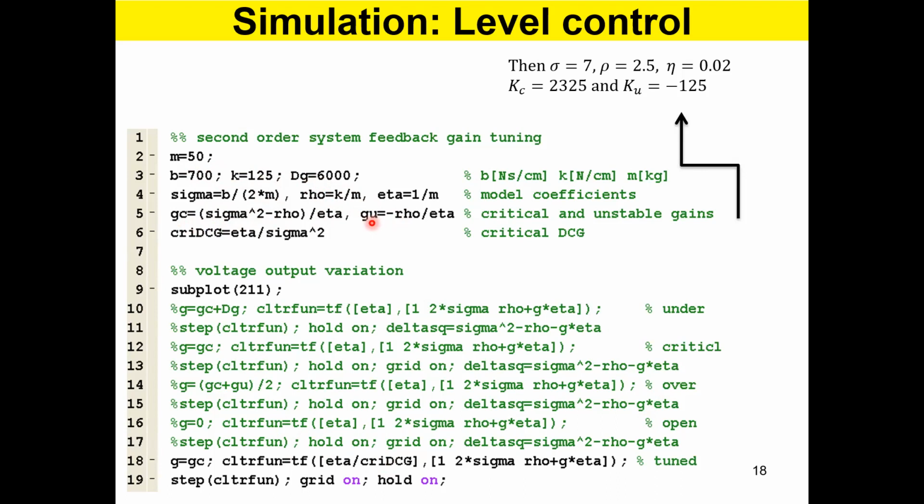And also remember the DC gain. Every system has a DC gain. That is what percentage of the input is actually coming to the response. If 100% is there, then the DC gain is 1. If 50% is there, then the DC gain is half. So that is also an important thing to know.